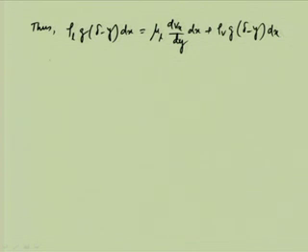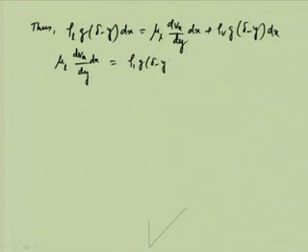So, we finally get that mu L dVx/dy into dx is equal to rho L g (delta minus y) into dx minus rho V g (delta minus y) into dx.